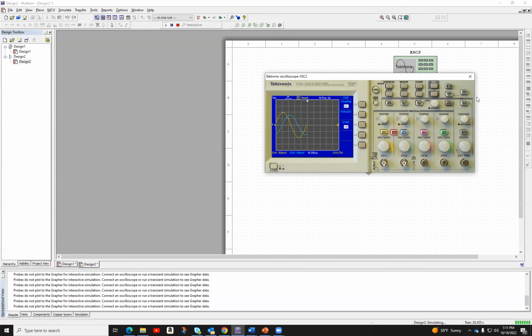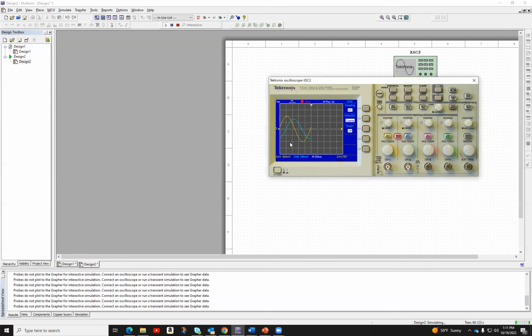But what I notice now, if I stop it again, is that obviously channel 1 didn't change. It's still 2 volts peak to peak, my input signal, still 1 kilohertz. But the output did change. Now the output is less than that, because you notice that channel 2 is set to 100 millivolts per division.